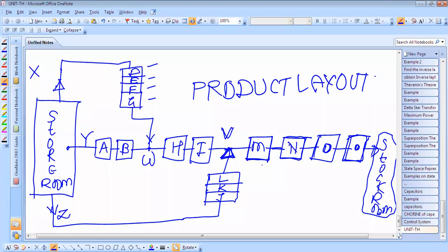The machines are scattered along the line. More machines of each type have to be purchased for keeping a few as standby. Suppose a problem occurs in one machine, then the standby machine can be placed in case of the faulty machine. If one machine in this line fails, it may lead to the shutdown of the complete production line.